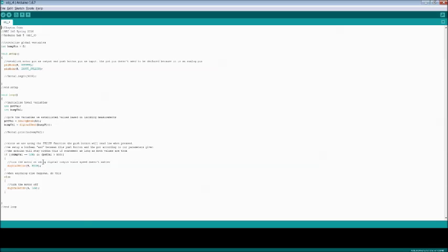In this case, I had the bumper switch pressed and the potentiometer above 500, so it will run what's in this if statement. In this if statement I have the motor turning on using pin 9 with digital write, because we don't care what the speed is, so it just needs to be on or off. Digital write 9 high, the motor turns on. When this statement is no longer true, it kicks out and goes to the else. Else means anything else is happening, so the else executes whenever this is not true, and it turns the motor off.